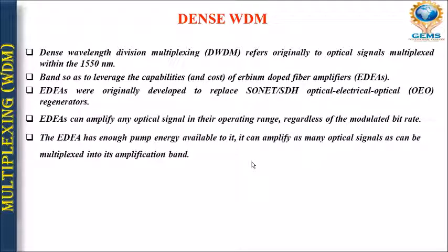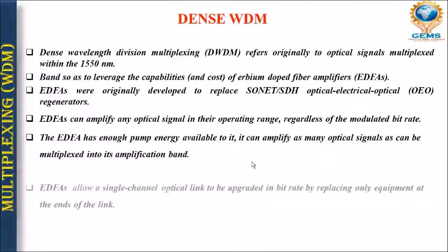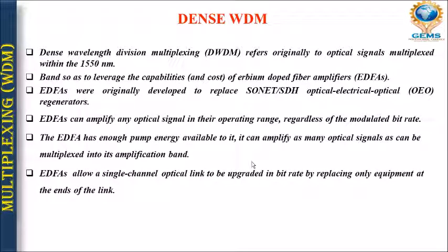If EDFA has enough pump energy available to it, it can amplify as many optical signals as can be multiplexed into the amplification band. This EDFA allows a single channel optical link to be upgraded in bit rate by replacing only equipment at the end of the link. So wherever we want to install dense WDM, EDFA is widely used.